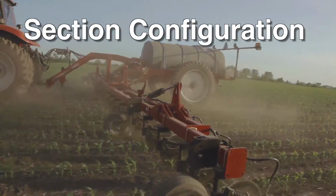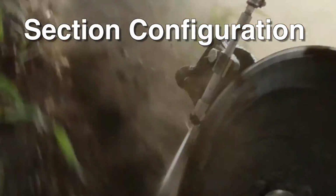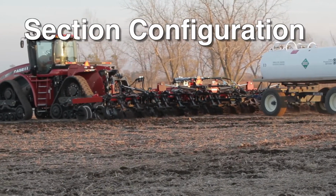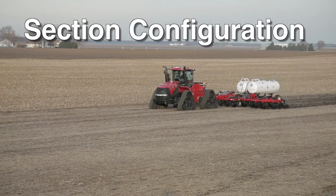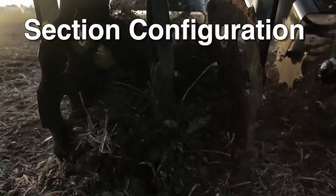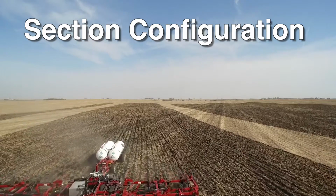Let's now configure sections. A section refers to a part of the implement in which all of the injection knives are supplied with ammonia from a section valve. Closing the section valve switches off the section. The implement has as many sections as it has section valves, which can be switched off. The first section is always on the left in the direction of travel. The second is on its right.